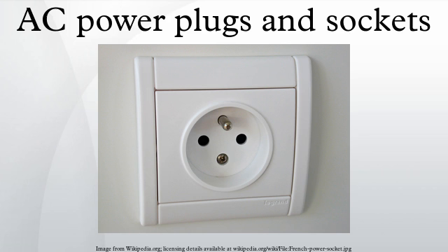Older sockets are so shallow that it is possible to touch the pins of a plug when the plug is inserted deep enough to get electrical power on the pins, while newer sockets are deep enough to protect from this kind of accident. Depending on the country and the age of the socket, these may have 4.0 or 4.8 mm sockets. The latter accept CEE 7/5 and CEE 7/4 plugs in addition to Europlugs, though without earth connection. Adapters, trailing sockets, and power strips designed to accept only Europlugs with 4 mm pins may also have plastic barriers in place to prevent CEE 7/17, Schuko or French plugs from entering.